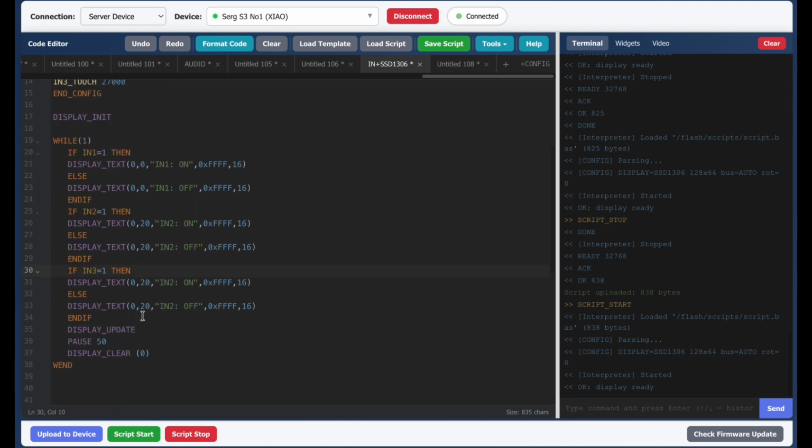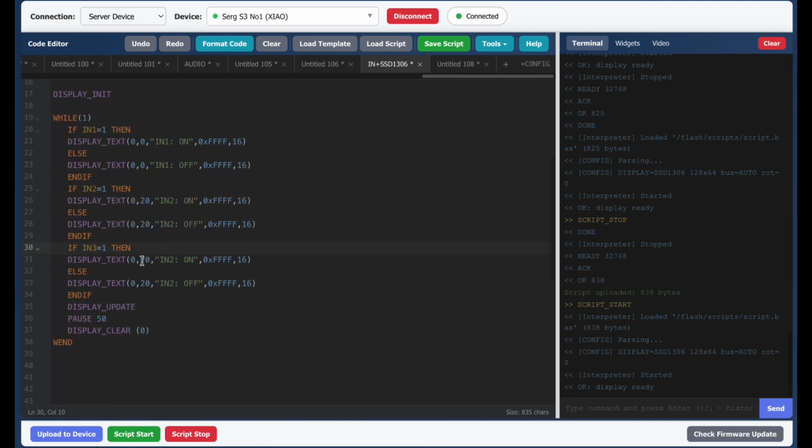When a finger gets close to or touches the electrode, the capacitance of the circuit changes, and the ESP32 detects it. The key advantage is that you don't need to touch the metal directly. The electrode can be hidden inside an enclosure with plastic or glass up to 2 or 3 millimeters thick on the outside. A touch on the surface will still register. This opens up some interesting design possibilities.